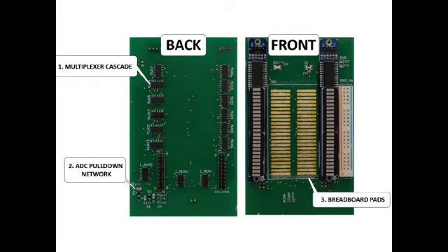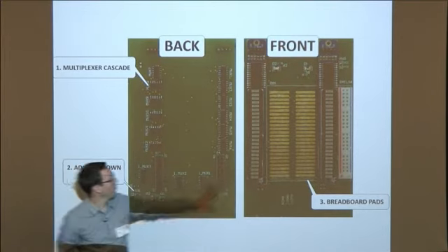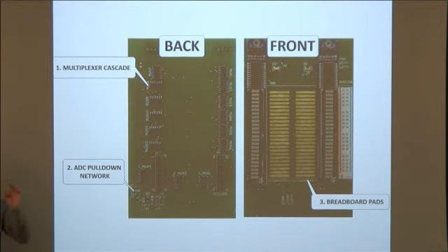Not sure you can tell much by this board, but here's a little detail under the hood: how do we make all of those connections? Well, we have a circuit board where you put your breadboard on here. So you peel back the foam, and then you put it on top of these pads. And we use Z-axis transfer tape, which is adhesive that has tiny spheres of conductive material embedded in it, which means it only connects in the Z-axis, but not X and Y. So you just take a single strip of that tape, put it over the board, put the breadboard on top. And then there are some mechanical issues that I'm glossing over, but that's the gist.